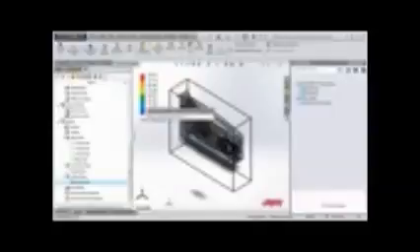This is due to the two resistor models we introduced, as well as the detailed model for the board. Also, connecting the housing to the board will create a conduction path from the components through the board and to the housing. The model will then interact with the ambient temperature through convection.